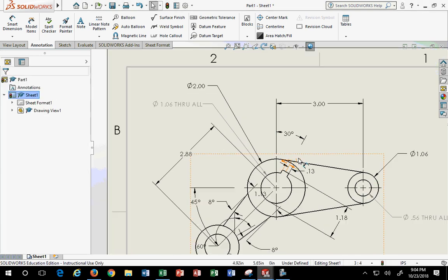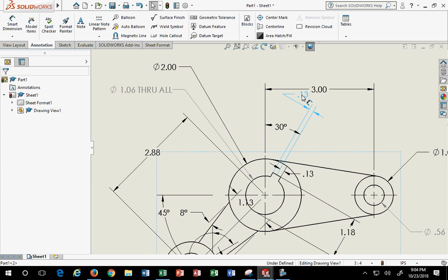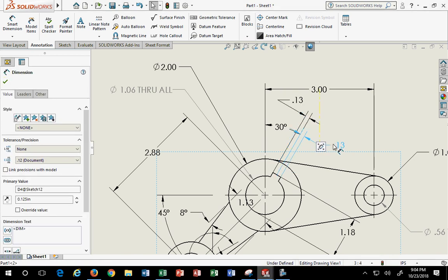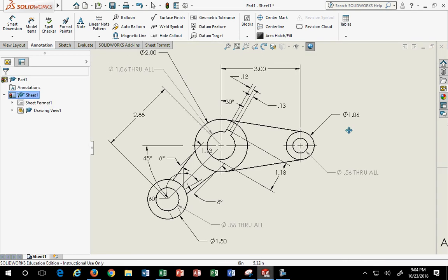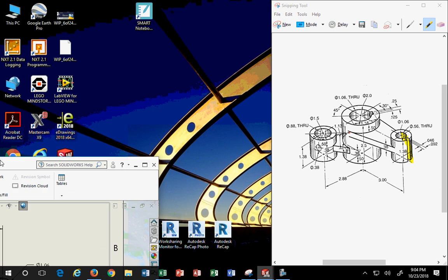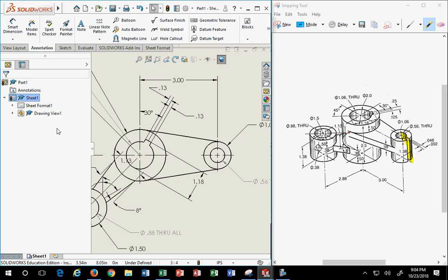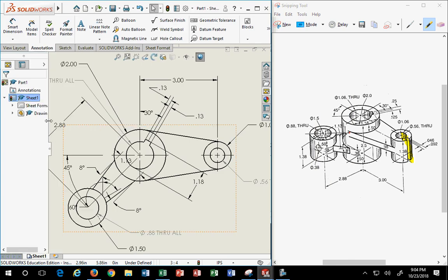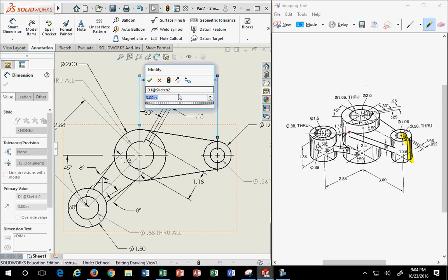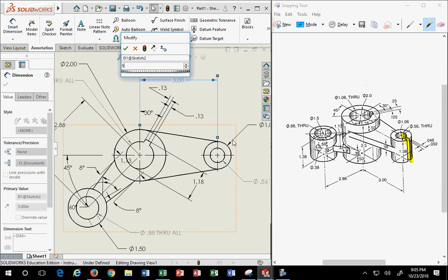These are literally all the dimensions I use there. So that offset that I used of 1/8 of an inch for this, it's in there. Everything is in there. Because these are all driving dimensions. They're not driven. These are drivers. So if I change this 3 to something else, it'll literally change my model. I'm going to make it 5 just to prove the point. Now you see? Nothing up my sleeves.